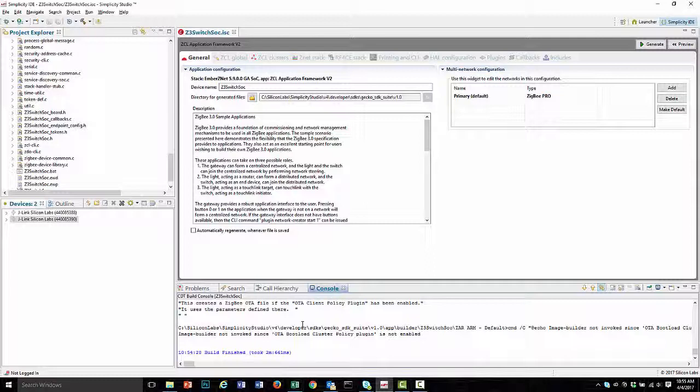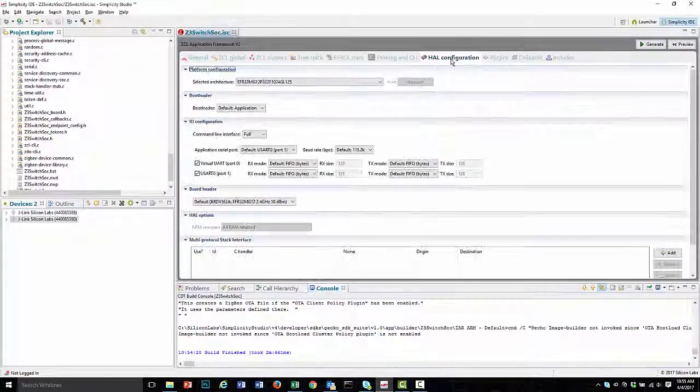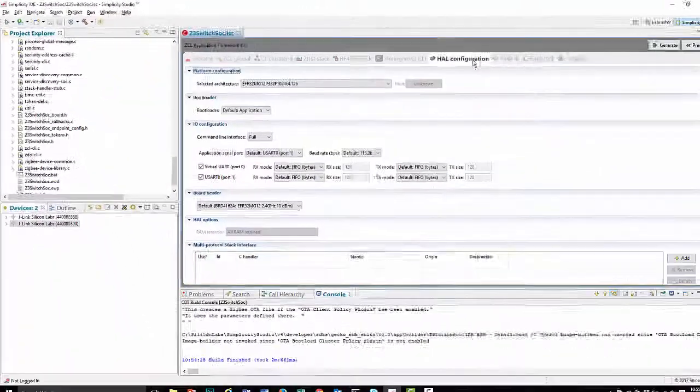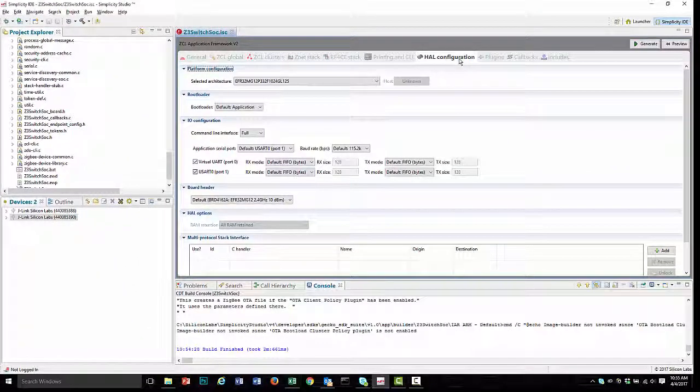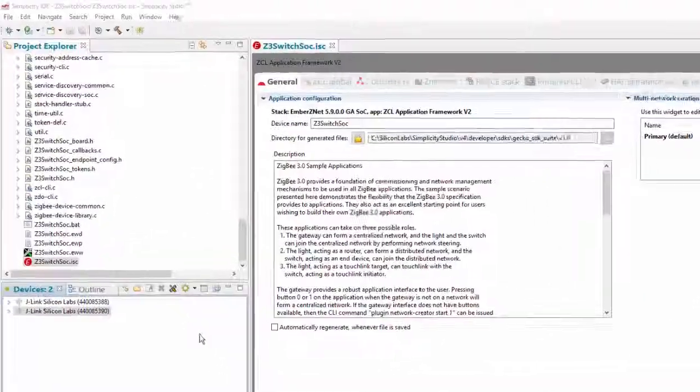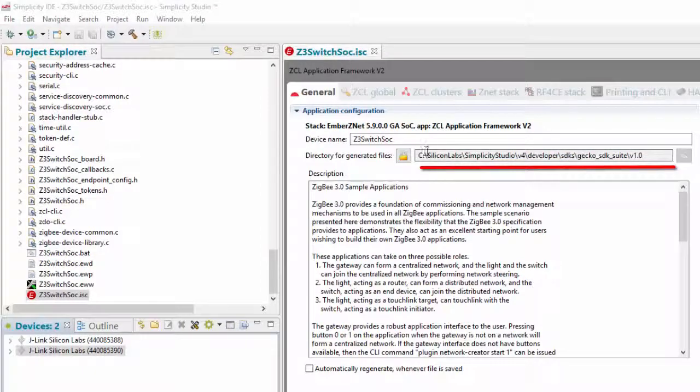Next, you will download the example to your device. All example applications require a bootloader, as reflected on the How tab. Silicon Labs strongly recommends that you use a bootloader, even in development, so that memory is allocated correctly. Silicon Labs supplies pre-built bootloader images for several common development platforms. The files are stored in folders under the project folder shown on the General tab.